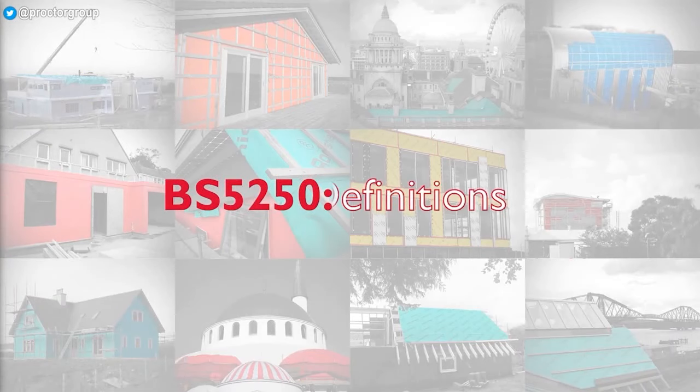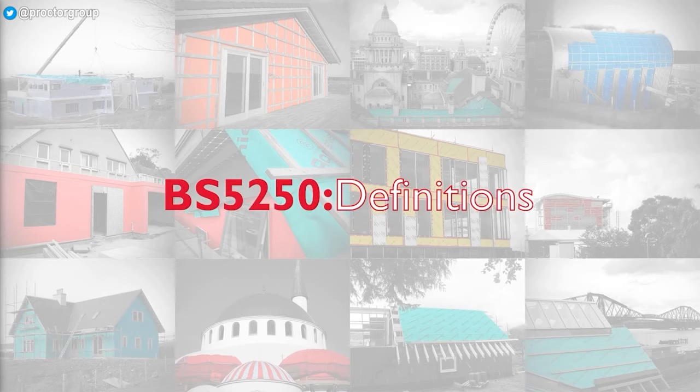BS 5250 definitions. BS 5250, the Code of Practice for the Control of Condensation in Buildings, outlines when and where membranes should be used, along with ventilation requirements that may apply. BS 5250 is actually undergoing updates just now and is reaching the public consultation stage. It was supposed to be issued this year, 2020, but we'll have to see how that goes under the circumstances. We'll be putting out a webinar covering the changes as soon as it's finalised, so please keep an eye out for that.